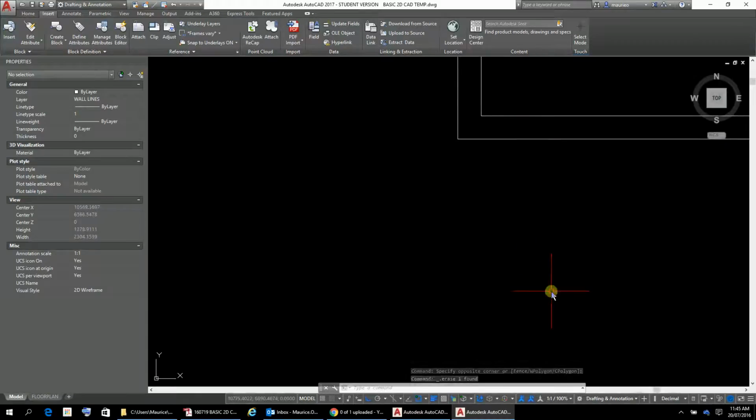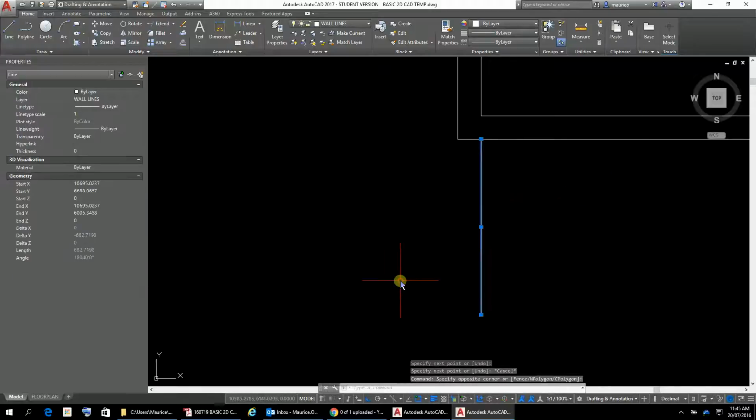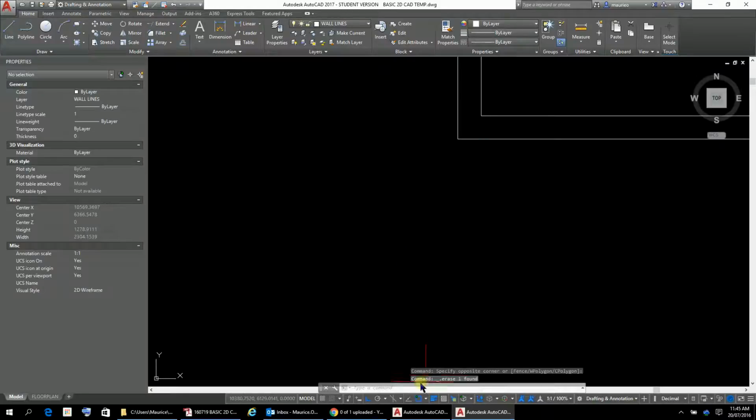So let's just have another look at that again. You can click obviously in the home up here, you can push L for line, or you can just type in L for line with your left hand or whatever hand's not on the mouse. So there's there, so just drag it down to the extend, it'll start there and carry on from there. That's a handy little feature that you could use sometimes, provided that you have, I think, the dynamic input turned on.